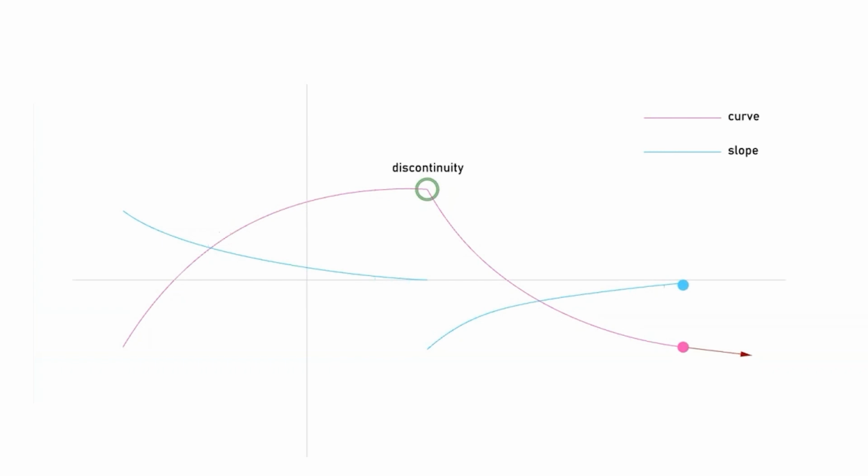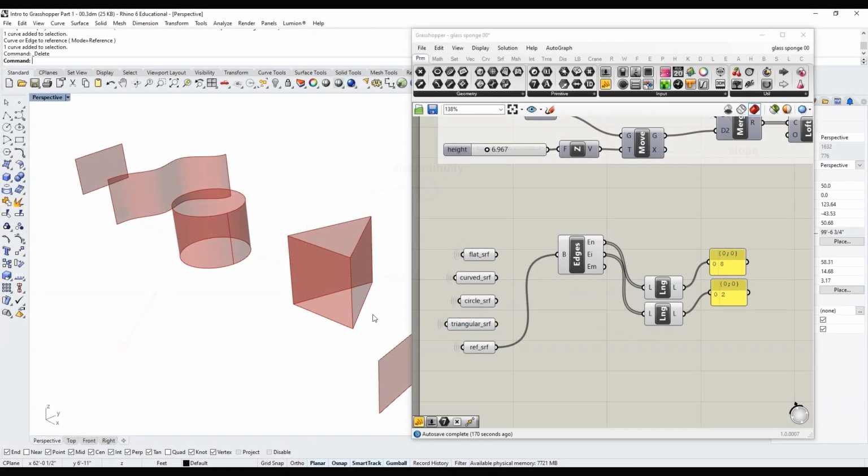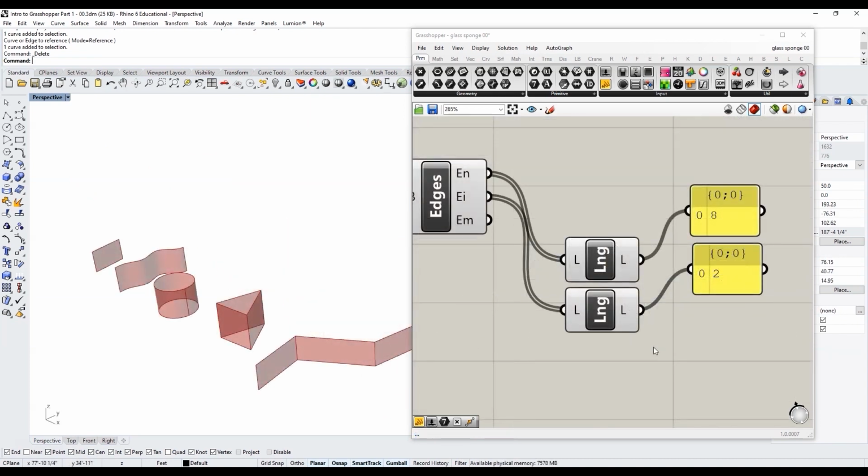And then even if the curve is curvy, if the curve's not continuous, I think technically when the tangency is not continuous, or when the slope of the curve makes a jump, when there's a literal break in the derivative of the curve. Anyway, everywhere there's a discontinuity, there will be a seam or a naked edge. But in the case of surfaces that wrap back in on themselves, there will only be seams whenever there's a discontinuity, and these seams are interior edges. So for the surfaces that wrap back, the number of naked edges is equal to twice the number of seams, since at every discontinuity, a new naked edge starts on both the top and the bottom, so times 2. And those will be the only naked edges because, again, it wraps back in on itself.